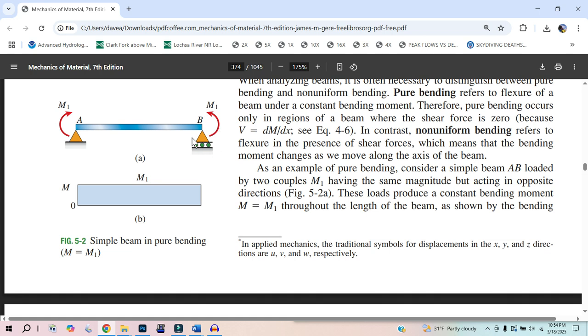And so here is a little bit of gold: anytime you see this, a moment is force times distance. So even though we're just saying, hey, this moment acts at this point B, I think it is very visual to actually imagine that this is two forces, one, let's say, down right here, and then one up right here. Because a moment still has to be a force and then a distance involved. And drawn like this, when you have a moment like this, it is a true couple. So you could say the couple applied.